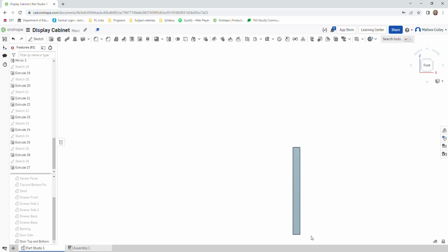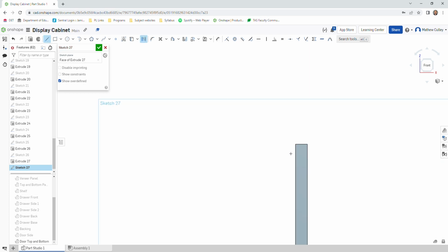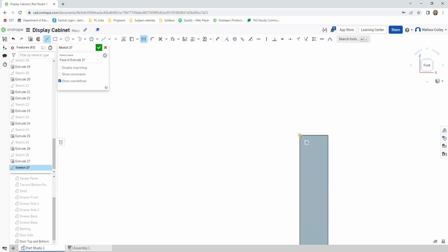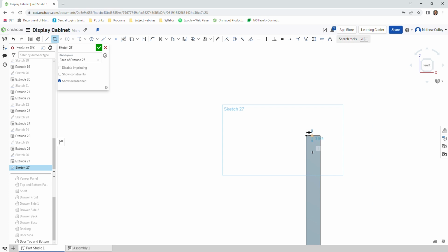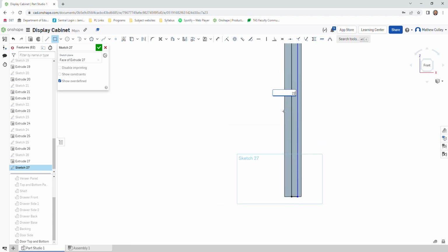And we just repeat the process like we did for the door side. So we'll start with our housing, sketch, select our face, L for line, Q for construction, left click on that corner once, come in, left click again, 8mm, escape, G for rectangle, left click on our construction point here, come all the way down the bottom there, left click again, and 226, enter, and 3, enter, press escape, left click on this geometry and delete it.